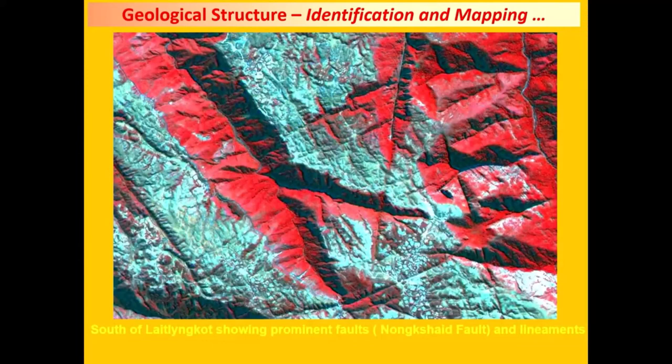So geological structure, to continue with, please understand how a fault or completely joint controlled surface topography looks like. It will look something like this. There are different crisscrossing joint sets, and you can look at the fault. So this line was continuing here, then it's not continuing. There is a curved line like this continuing, and this is the fault line, and this way it is absent. So it's because the repetition or omission of the beds has happened.